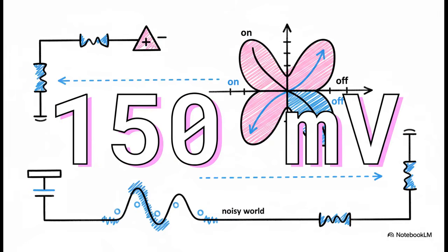So to make this a little more concrete, just imagine a sensor that's monitoring the liquid in a tank, where splashing around creates a ton of noise. If the desired trigger point is, say, 1 volt, engineers might design a deadband of about 150 millivolts. And that ensures that even if the liquid sloshes around, causing all these little voltage changes, the output stays stable unless there's a real, significant change in the liquid level.